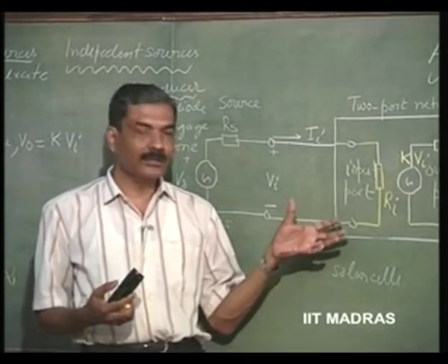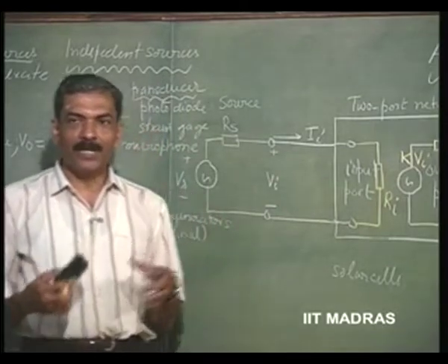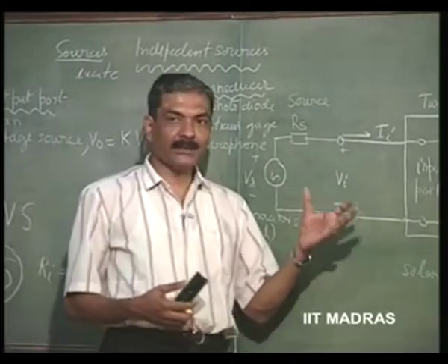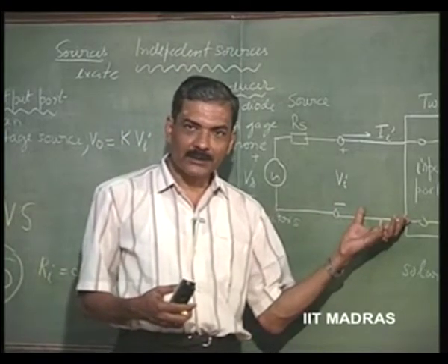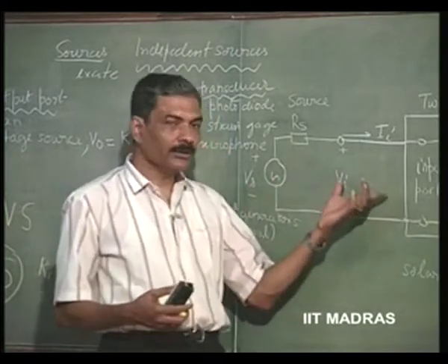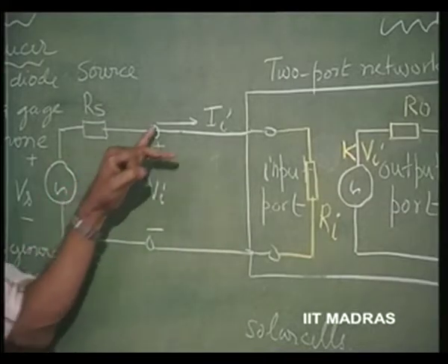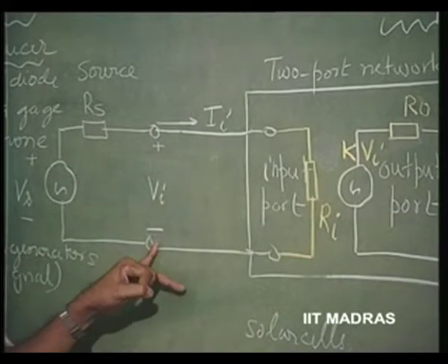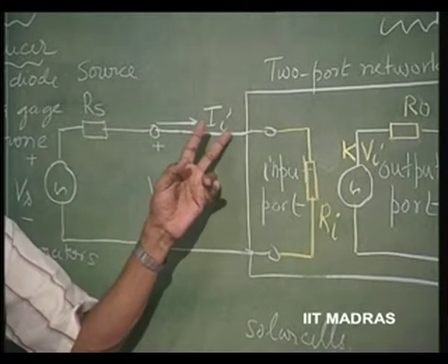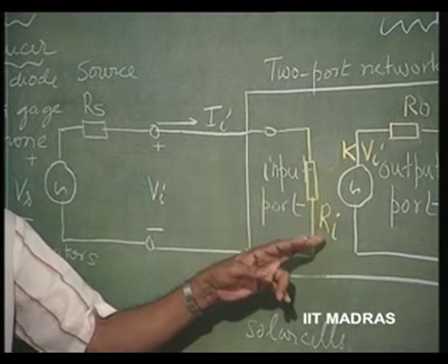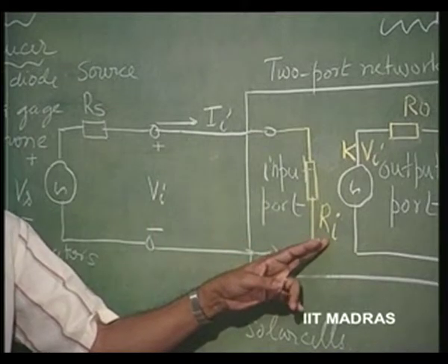The value of Ri should be very large. Now, large compared with what? Any comparison here in practice should be made with reference to what it is going to get as input. This input voltage here is going to remain undisturbed as Vs as long as I I is 0. That is possible only when Ri is very high, compared with what?